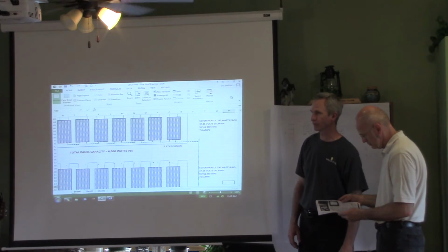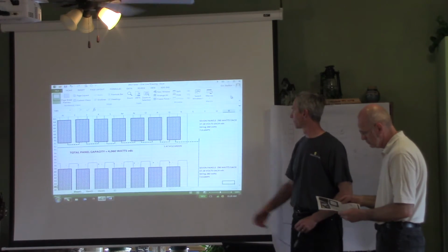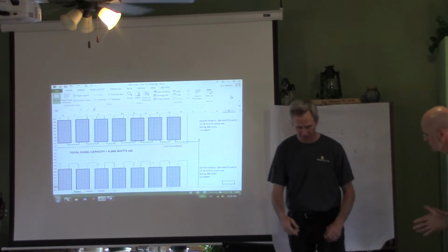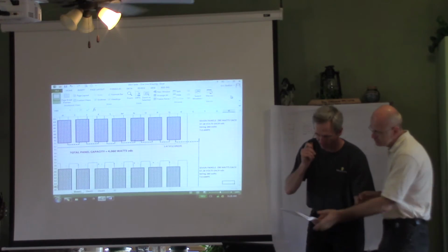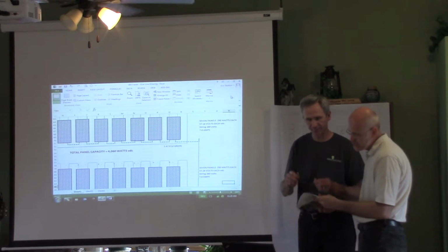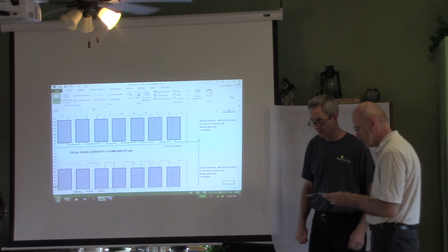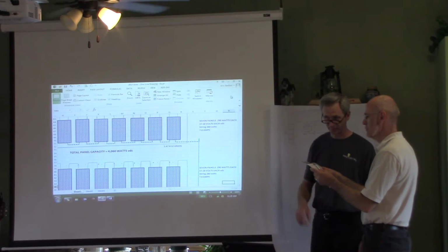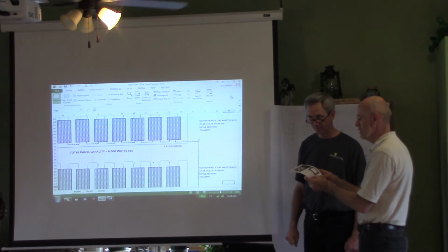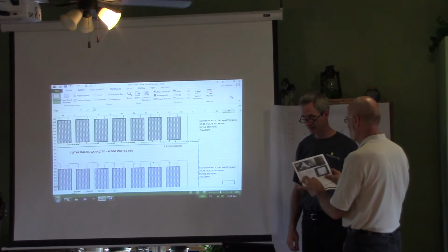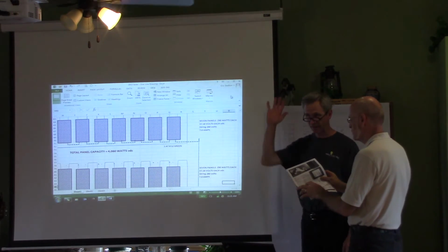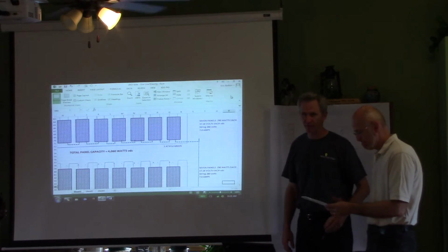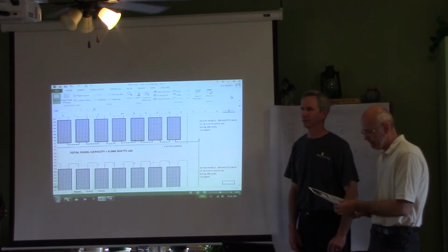So he said, well, first of all, we've got to add things up. Each of these panels, if you look at the spec sheet, has what's called the voltage at maximum power point, VMP. Voltage at Pmax, VMP. What's the amount? 37.18. Yep. So Dave said, well, it's great you want 14 panels, but what's 37 times 14?